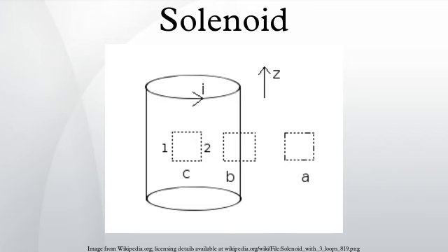Using this, the magnetic flux density is obtained. Inductance. As shown above, the magnetic flux density within the coil is practically constant and given by B = μ0NI/ℓ, where μ0 is the magnetic constant, N the number of turns, I the current and ℓ the length of the coil. Ignoring end effects, the total magnetic flux through the coil is obtained by multiplying the flux density by the cross-section area. Combining this with the definition of inductance, the inductance of a solenoid follows as: